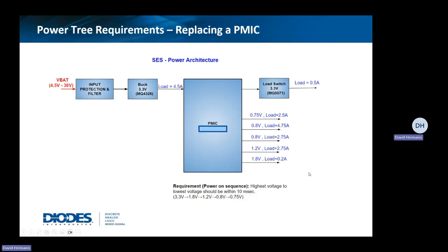So they are really slick parts. The downside to these, in some cases, is the fact that, number one, they're expensive. Number two, they're proprietary. So now you have two parts on your design, because the SoC or the MCU, typically, you're never going to be able to second source. But when you actually add the PMIC in there, there's another proprietary part that just basically increases the risk of having supply chain issues if we get into a constrained market again.